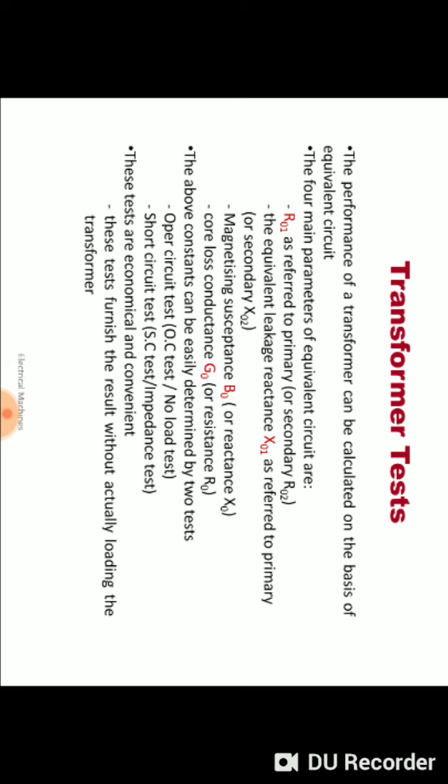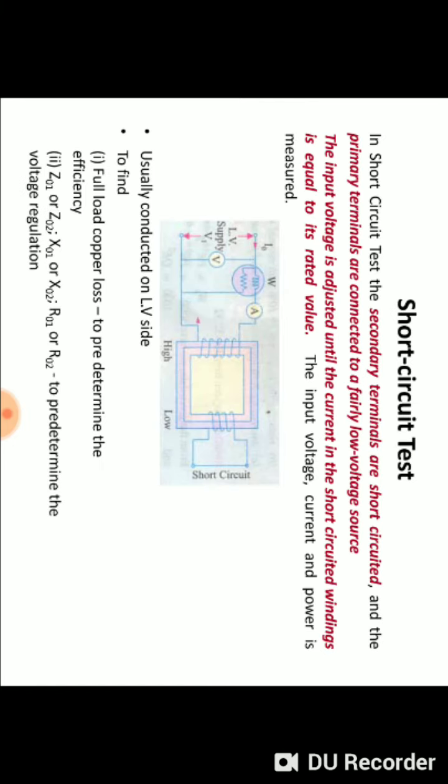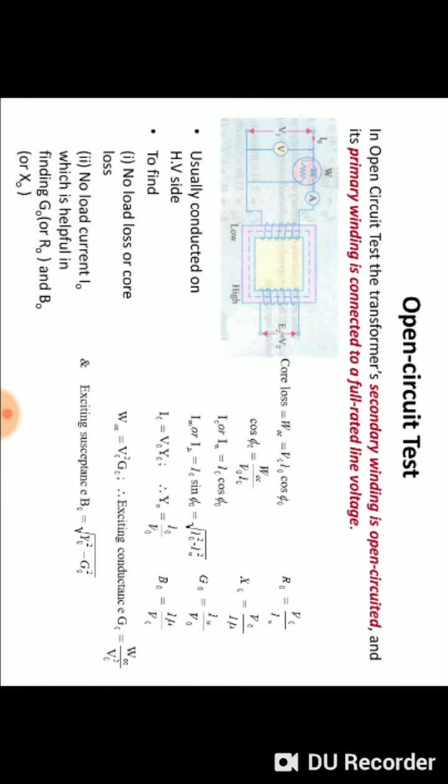These tests are nothing but to check the performance of a transformer, one of which is the open circuit test of a transformer. As we can see from the diagram, in case of open circuit, we apply rated voltage and rated current flows through the transformer primary side.